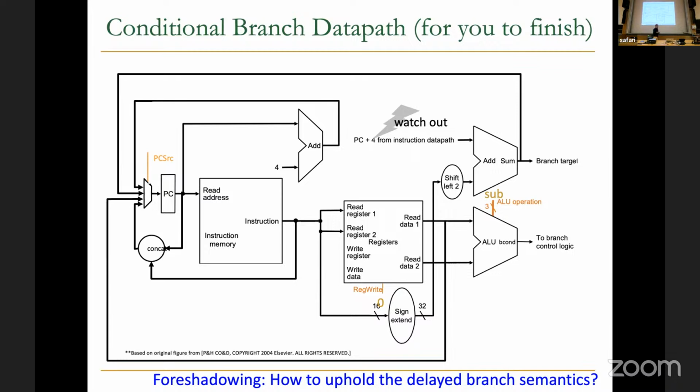You should never change the interface, assuming a particular implementation. And that's what the original MIPS designers did. Unfortunately, technology evolved in ways they couldn't have predicted. As a result, architectures like MIPS and SPARC unfortunately have to implement this delayed branching forever. Because once you have it, you cannot remove it, right? Okay, that's why you need to be careful in designing the ISA.